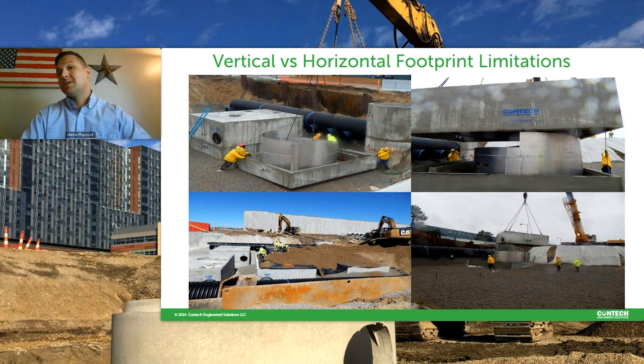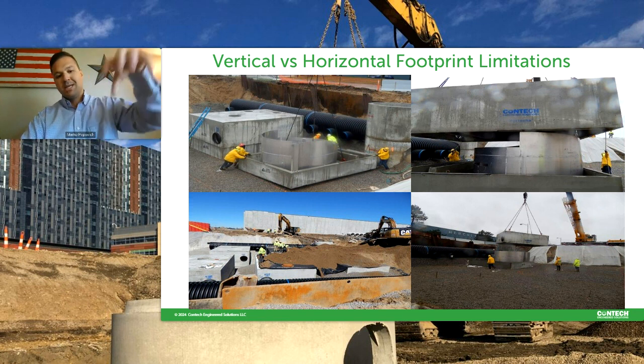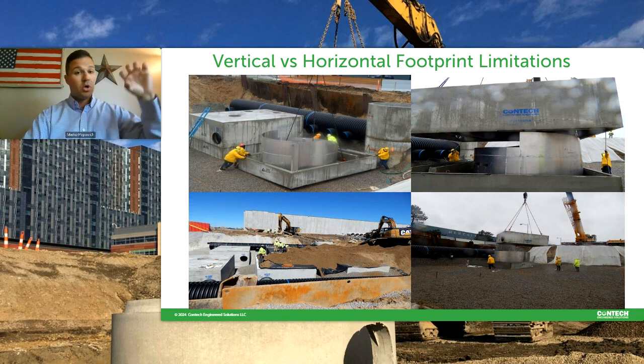That is something we as an organization try to avoid. We always try to, whether it's a vault, whether it's a manhole, to really set those internal components directly in the structure. So when it is out on site, the end user is putting it in, it sets no different than a typical stormwater structure, whether that's a diversion bypass structure or anything else. They can take it off the truck, put it in the hole, inlets labeled, outlets labeled, they can grout their pipes in, and they're good to go.